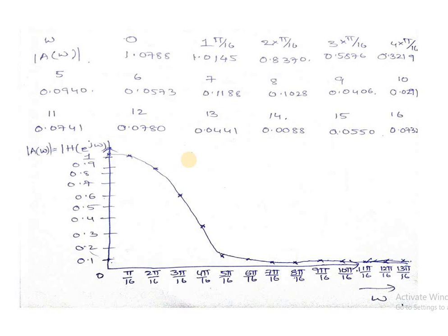And in the third step, based upon the given windowing sequence, we have converted the non-causal, or infinite impulse response filter, into a finite impulse response filter by multiplying the suitable windowing sequence, that is a rectangular windowing sequence given here in this case.